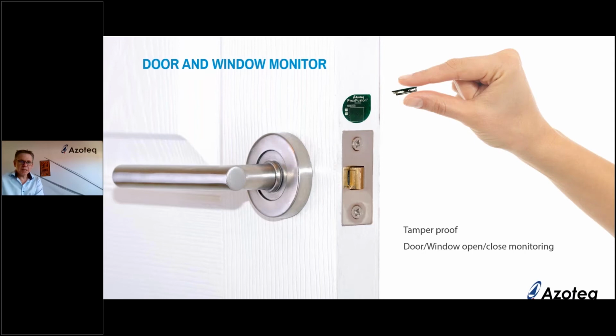In this instance, if the door frame is made from a metal or an aluminum material, you simply use the door frame as your target material. Otherwise, if you have a non-conductive frame like polycarbonate or wood, just apply a small metal foil or metal part to the door frame that you can use as the contact sensor.